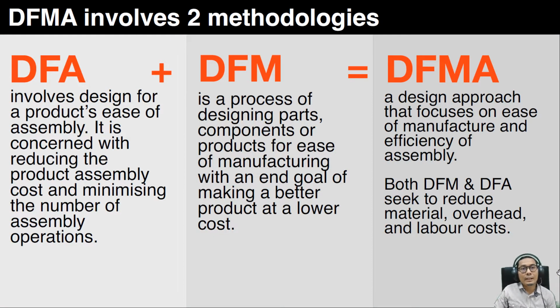And then DFMA involves two methodologies, which as I mentioned before, are DFA and also DFM. So what is DFA? DFA involves design for a product's ease of assembly. A stands for assembly. So it is concerned with reducing the product assembly costs and minimizing the number of assembly operations.